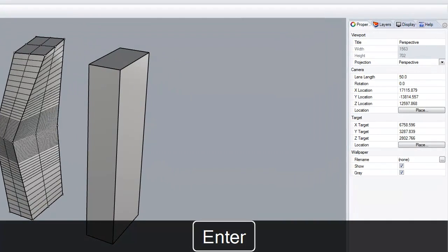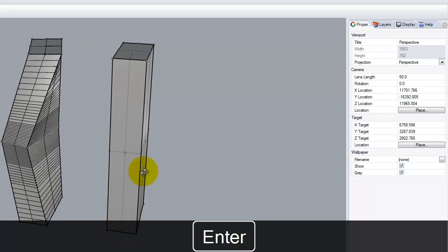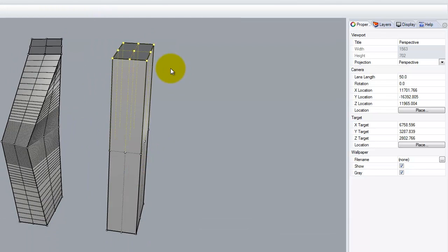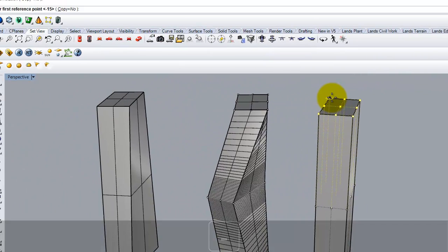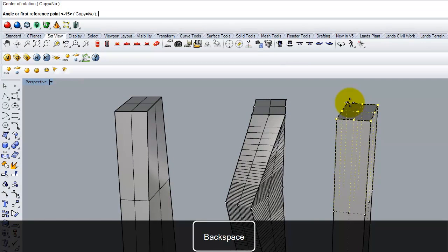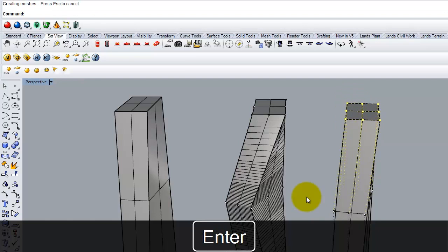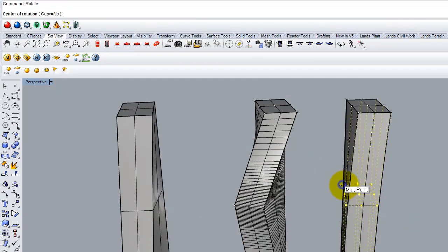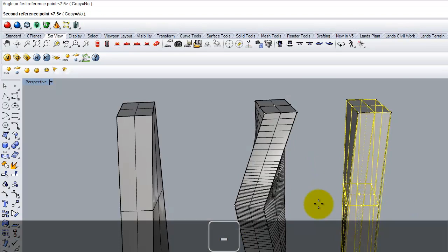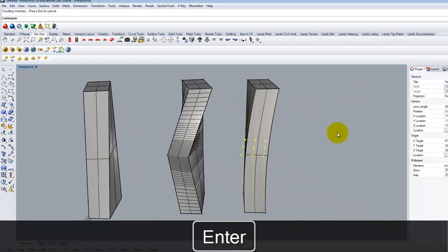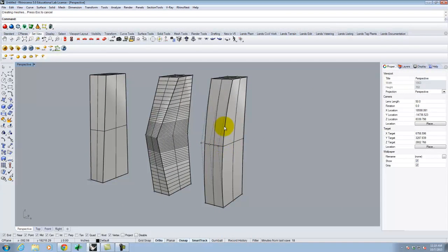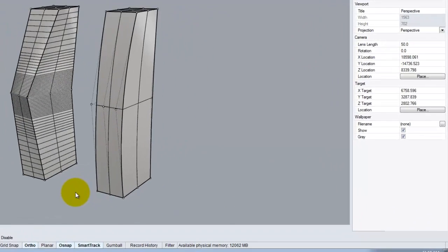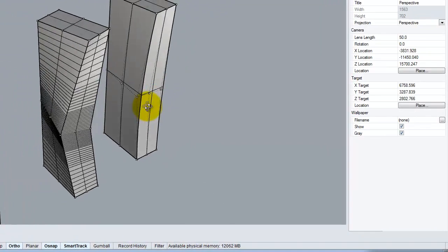I'll go ahead and hit enter, region to edit global. So same points. And if I select these and I go to rotate, and let's do it not quite so far. So let's do minus or 7.5 degrees. And let's take this and we'll rotate negative 7.5 degrees. Right? So when it's a 2-degree curve, you see how now I have a smooth curve instead of the angular. So by just changing the degree, I'm getting a very different set of curvature.